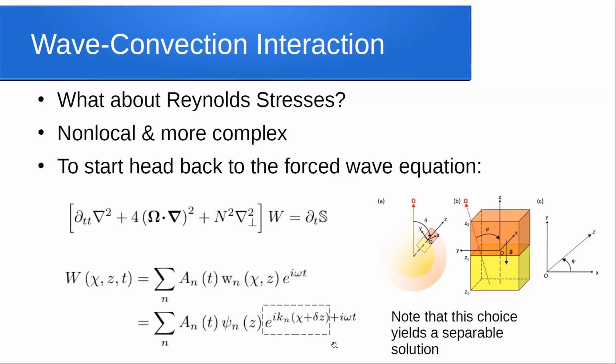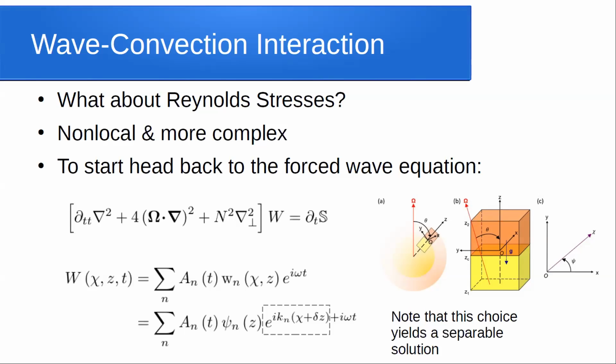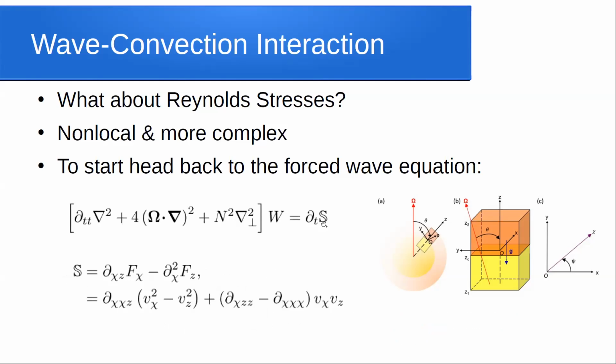Doing that, you can then solve the system. And oh yes, so what you have here is your source function. So this includes all your Reynolds stresses. If you have them, there's entropy stresses or the buoyancy stresses, but those are typically small in these systems, even in stratified systems. So we'll only really consider the Reynolds stresses in this term. And that looks like this. So it's basically your Reynolds stresses here.